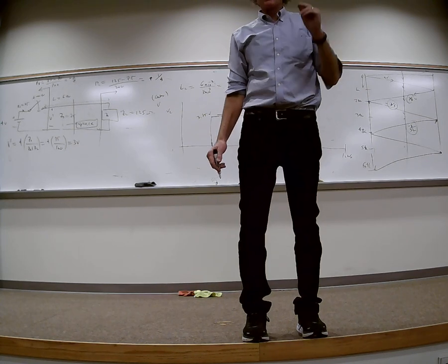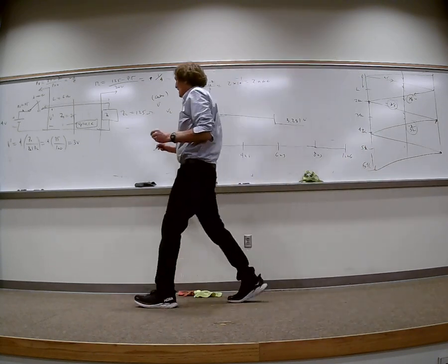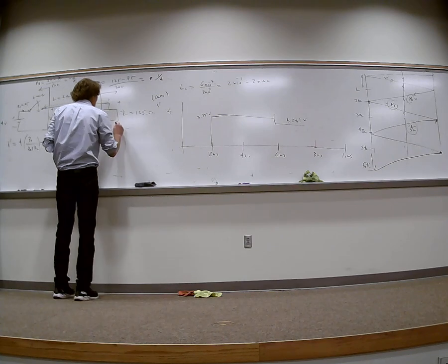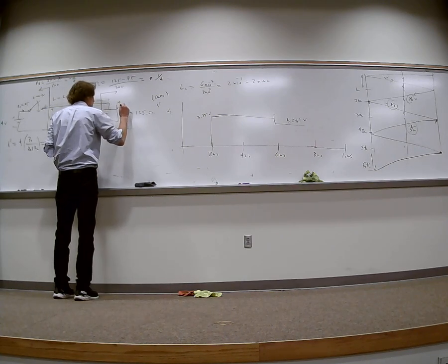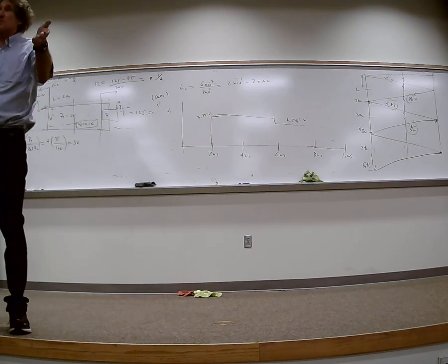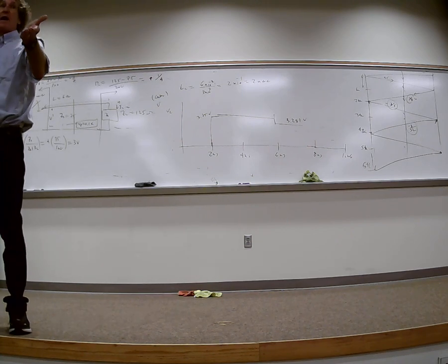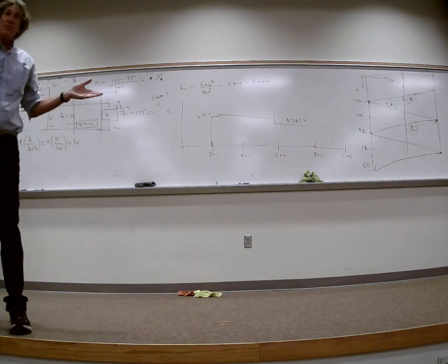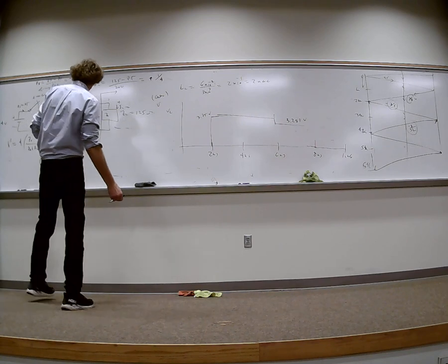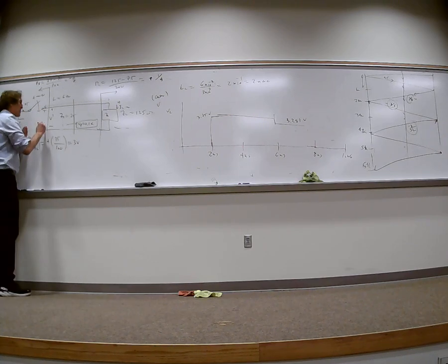Now, here's the question. If I asked you for the current that would be at this load right here, how would you get it? If I asked you for I load versus time, just talk to me. It's as obvious as it seems. Do you know the voltage at the load? It's right there, right? How do you get the current? Divide by the load. Do you all follow me? That's it. That's all you do. Now, if you ask for the current at this end, this gets a little interesting. All right, hear me now. Very carefully listen. You need the voltage here at the sending end.